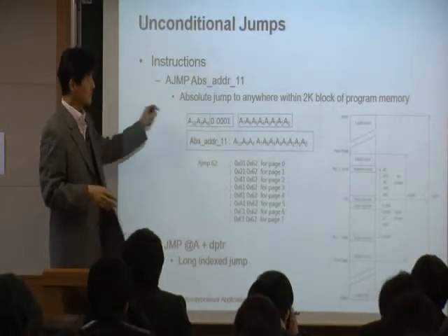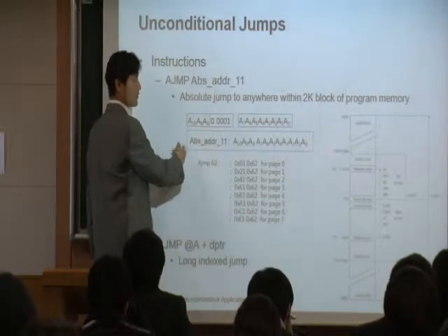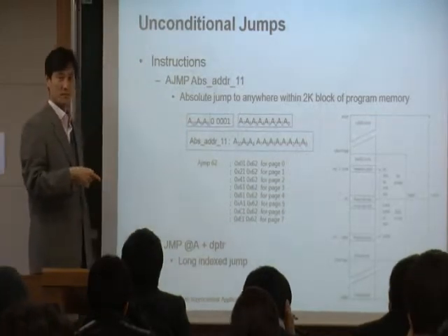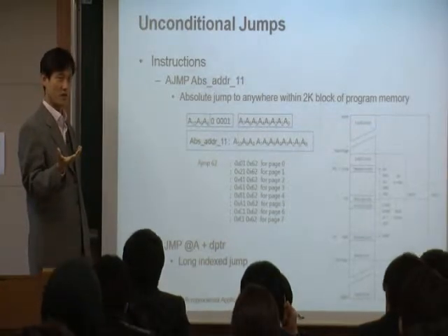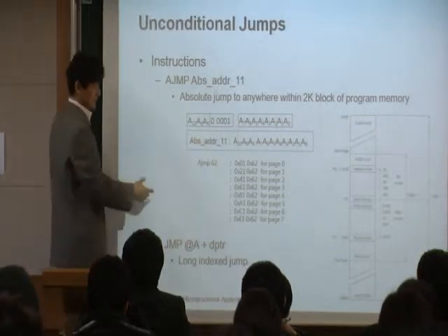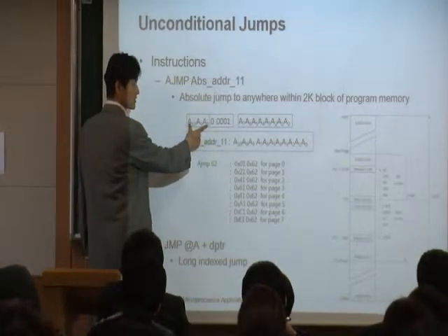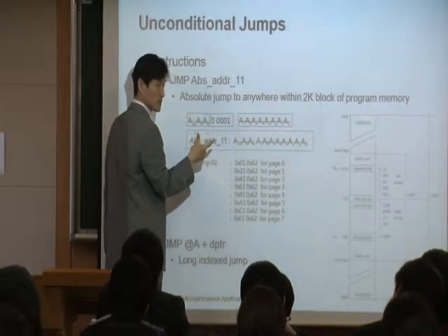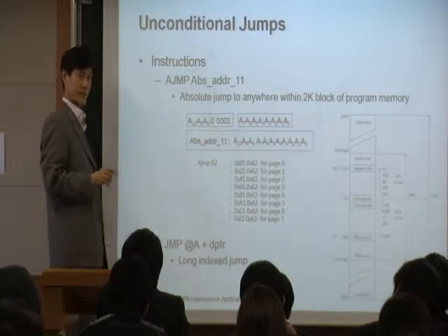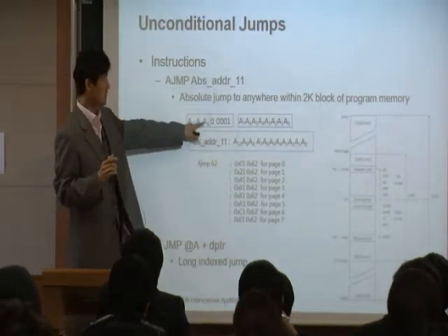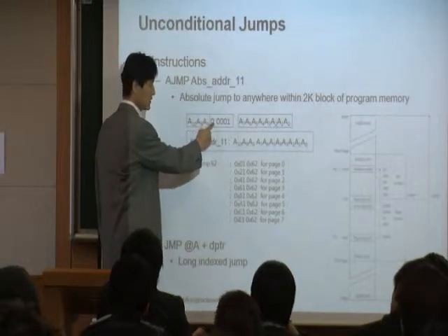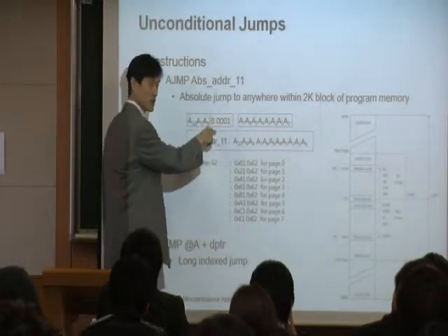So what does that mean here? For other instructions, typically the first byte is the opcode. In fact, you can think of this one the same way, except the first 3 bits are part of your address. So now let's pick an example. Let's say we have 0, 0, 0 as an example. In this case, what would be the number for this first byte? 0, 0, 0, 0, 0, 0, 0, 1, so it's 01.